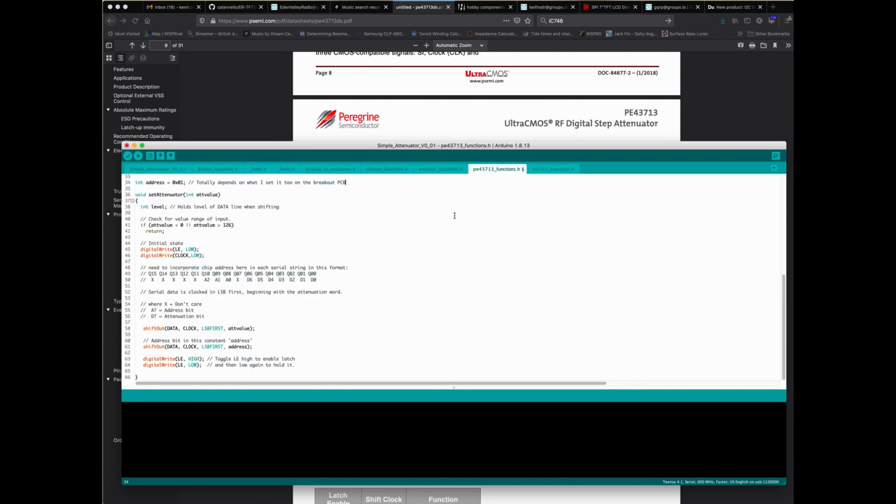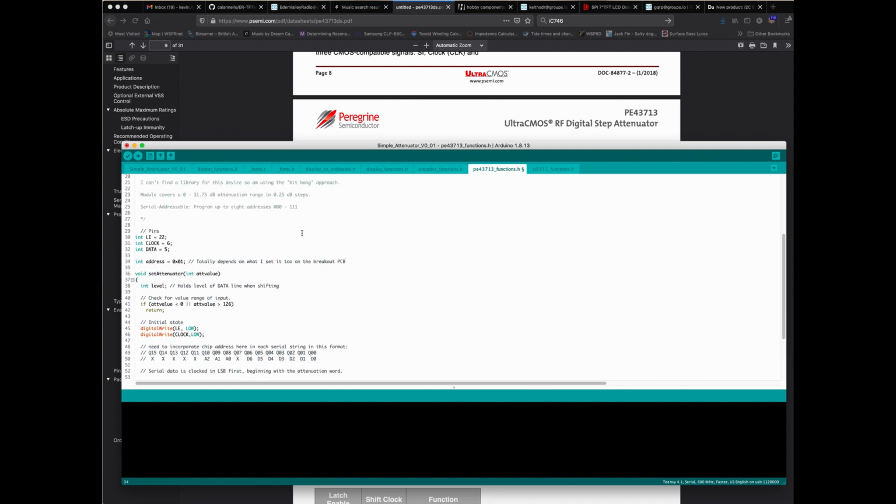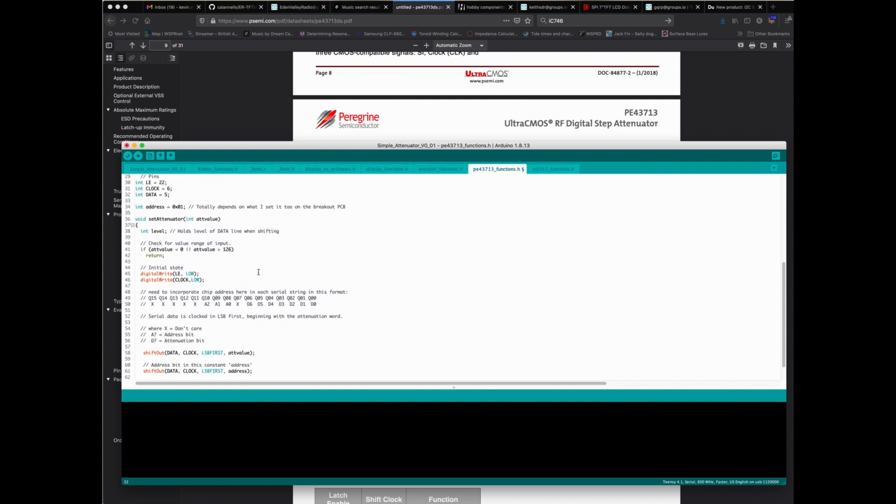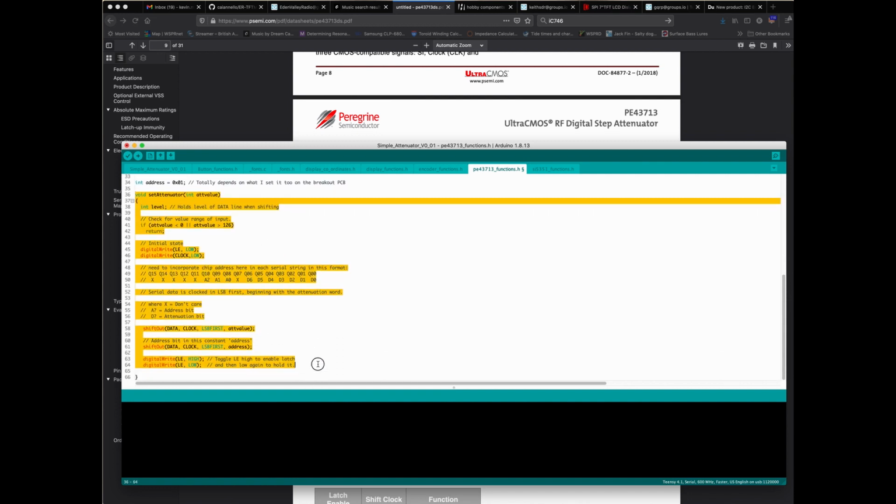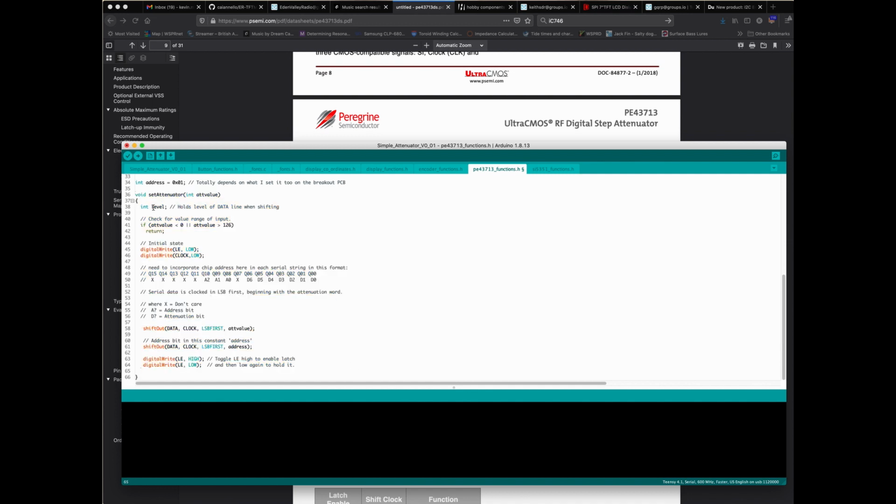But the main guts of it really is this section here, where these are the 3 pins that I'm playing with. Output to the rear header on the hardware. I've selected to set the address at 1, and I've matched the jumpers on the hardware to suit. And then I've just got this very, very simple block of code which sets the level.